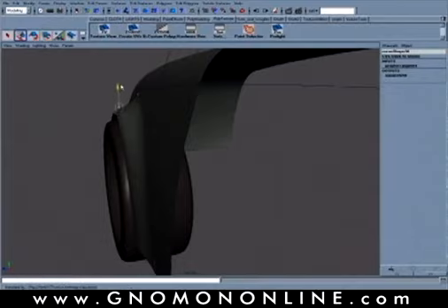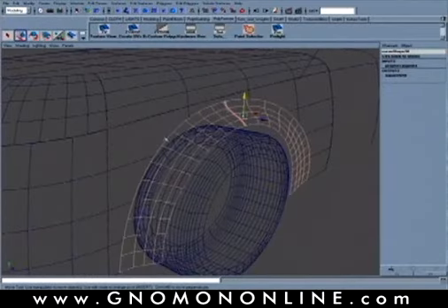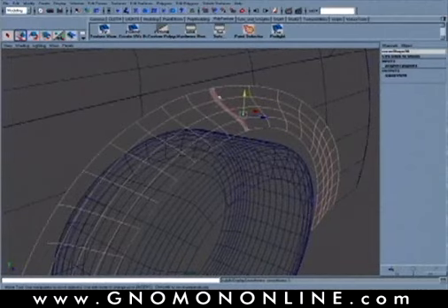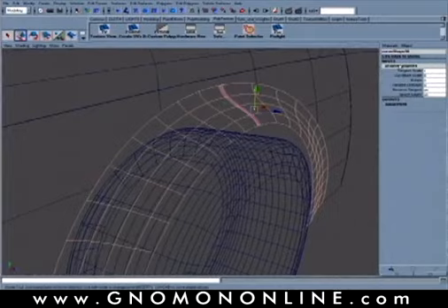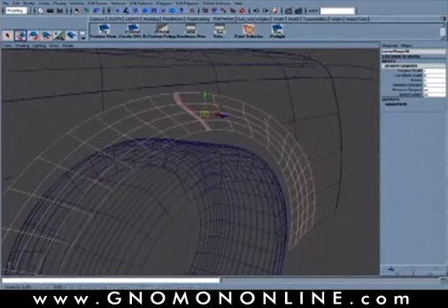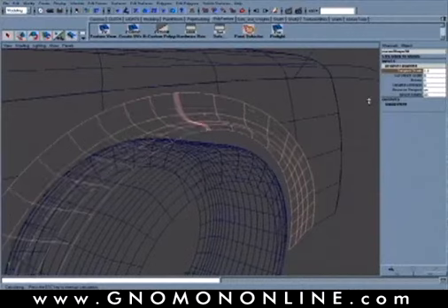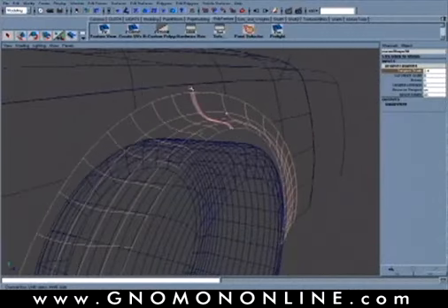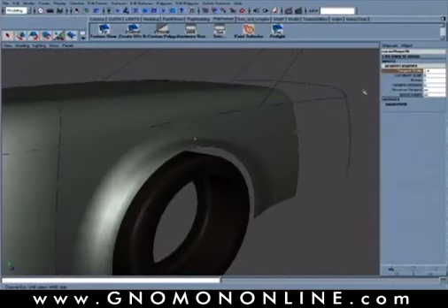You could also scale your project tangent curve, okay, meaning that original curve that I used to project tangency along that surface. So this one is still sitting here, and you still have your project tangent slider, so if you change your tangent scale value, you can drag this up or down. And again, we're just feeding into the profile curve that was used for the square, and that is then modifying both of the resulting curves.